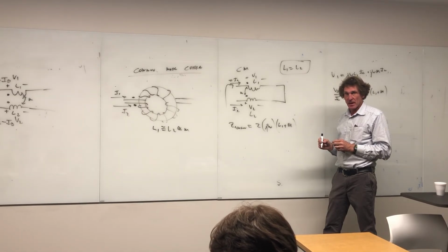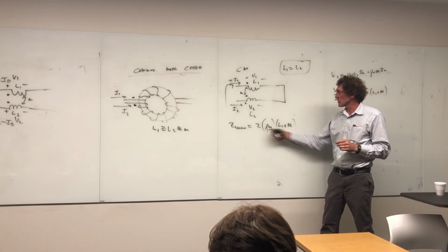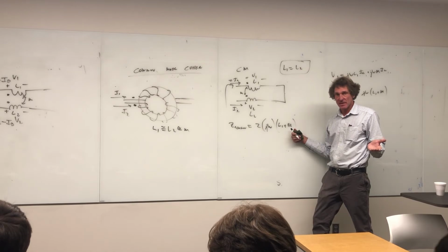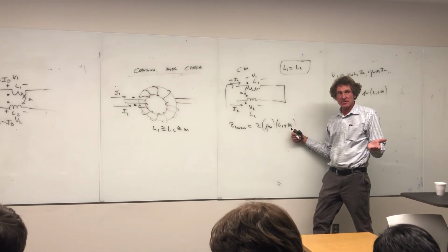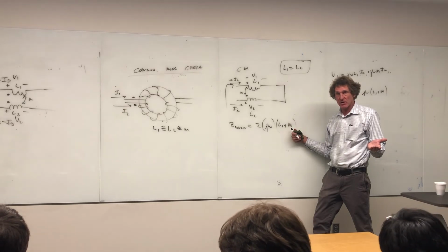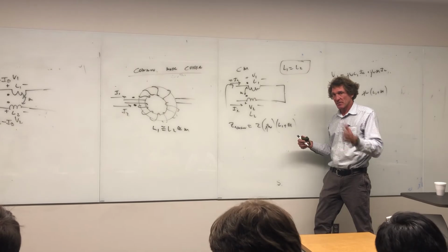Follow me? And that would be the impedance that would be against common mode current. When this is large, like 10 to the 8th or so, then that's a large impedance that's going to stop any significant amount of current from getting through there. You're going to have to go with me on this one as I make it clear with the differential.